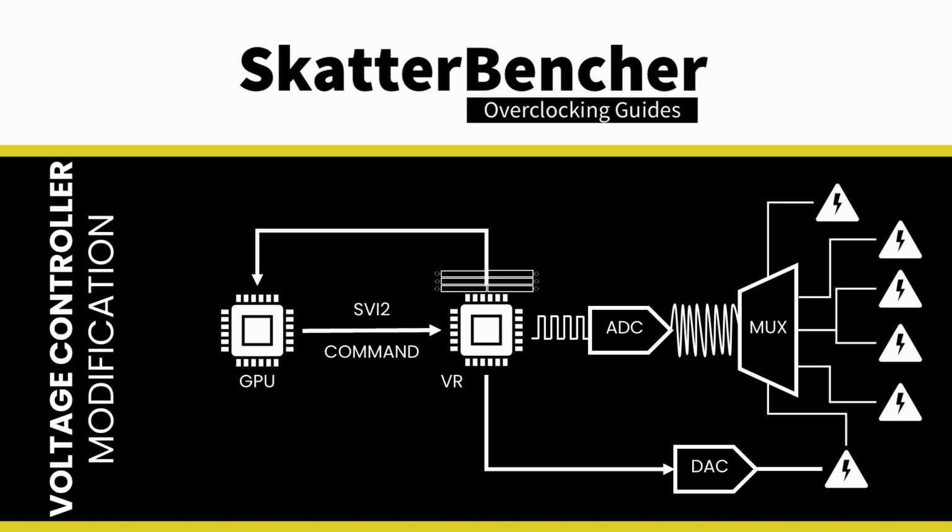The GPU will then read those registers back via the SVI2 interface and adjust voltage requests accordingly. The reported information via the ADC includes sensed GPU and SoC voltage, maximum capable GPU and SoC current, and slew rate for GPU and SoC voltage.